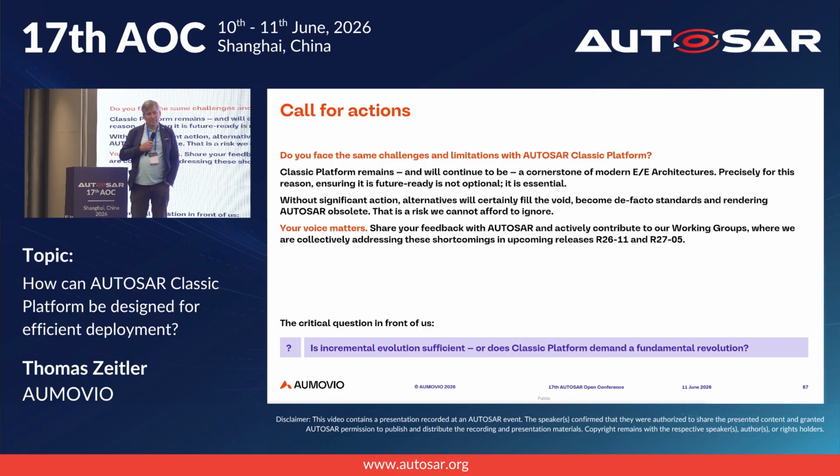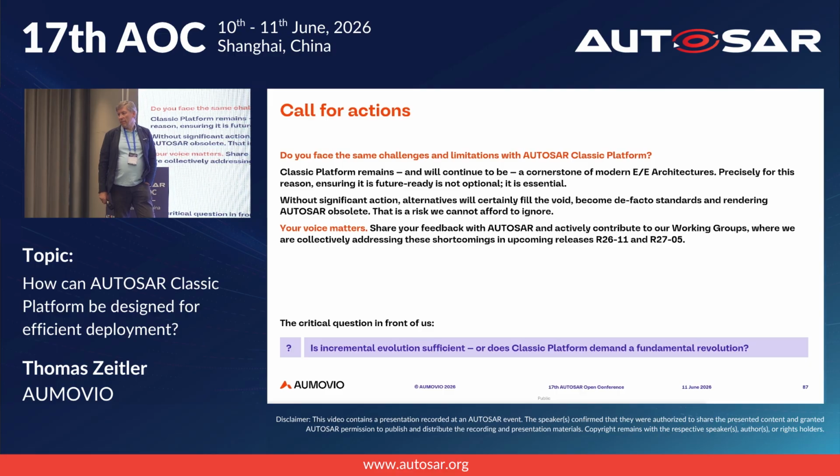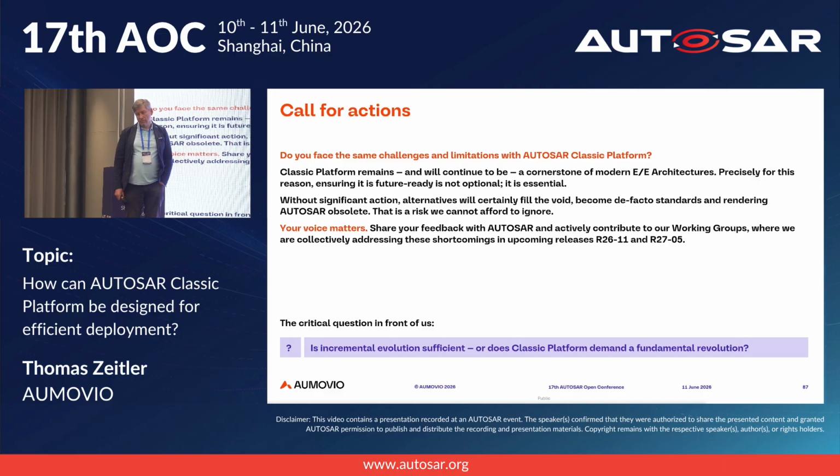so that if you don't touch the configuration, you already have a meaningful behavior of the ECU from the beginning, and everything fits together. The second thing, where Martin Lund is also working together with the AUTOSAR organization, is to try to have ECU classes. Depending on the ECU size, it should help you by making a proposal for which features to use. Like if you have a CAN ECU and you want to do security, you are automatically proposed to use SecOC, for example. Or if you're using an Ethernet ECU and you want to do security, you are proposed, for example, MACsec or IPsec. Also for safety, we have different end-to-end profiles, depending on the payload on the bus, so that if you use CAN or Ethernet, the correct end-to-end profiles are proposed.